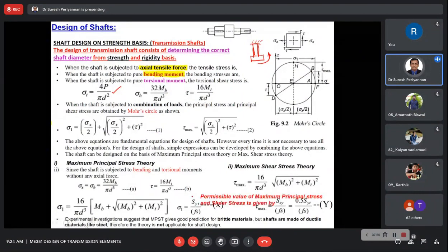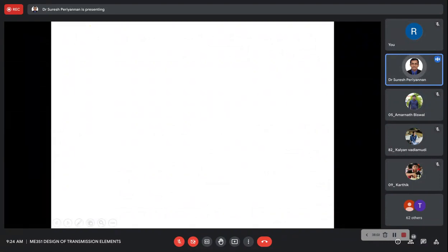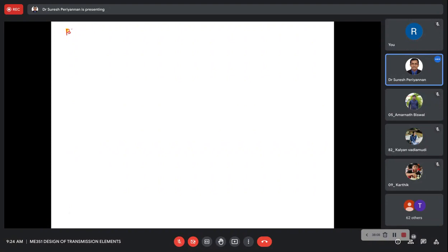Anyway, just a recap. No problem, just one minute. What is the bending moment governing bending equation? M by I is equal to sigma b by y, where y is equal to d by 2 and I is equal to pi by 64 into d power 4, right?